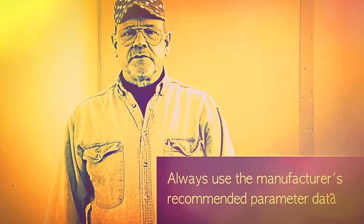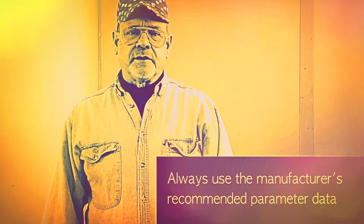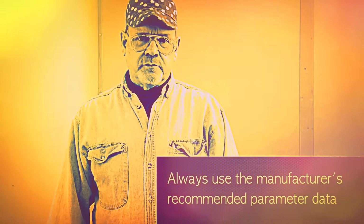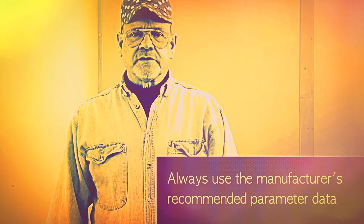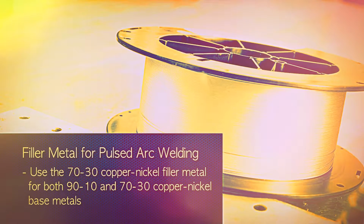We'll be using a particular pulsed gas metal arc power source and wire feeder. It's important to note that there are many manufacturers of such equipment. For the equipment we're using, the parameter data is what we obtain from the manufacturer. In every case, check with the manufacturer of your equipment to get the best parameter sets for welding the copper-nickel alloys. In this segment, we'll do pulsed gas metal arc welding with 70-30 copper-nickel welding wire.